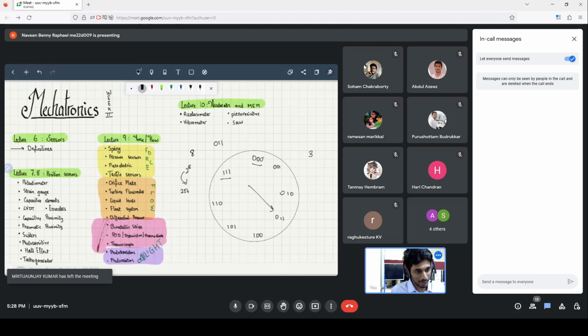This is not good because we are essentially getting a massive mistake in reading the wheel. We are literally completely out of phase with the reading. Therefore, we kind of want to choose digits in a way that there is only one bit of change in both directions. Does the motivation behind this make sense?